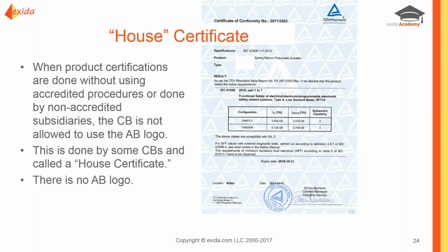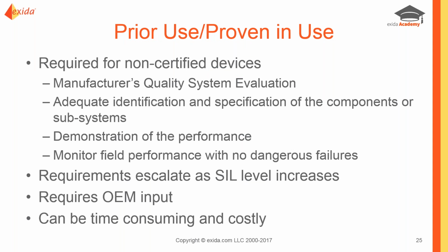This next one is just an example of a certificate. This is certainly a qualified certification body in some locations, but not all locations are actually accredited to do the SIL verification. So in this particular example, you'll notice there's no accreditation body logo on the certificate. So look for that kind of thing.